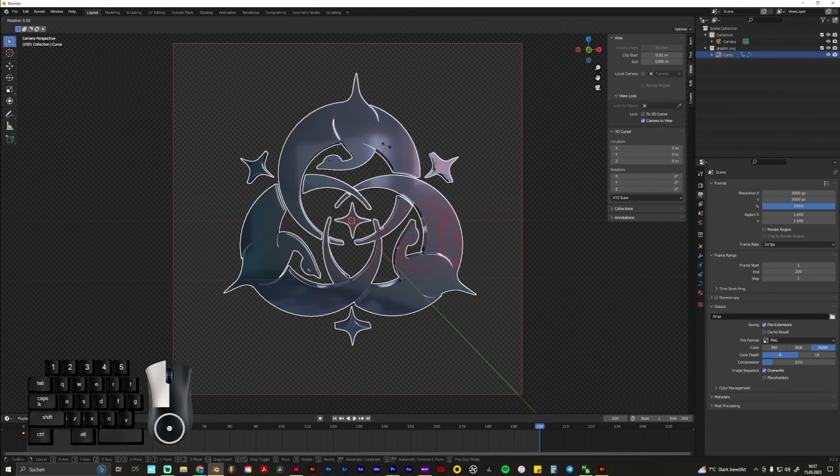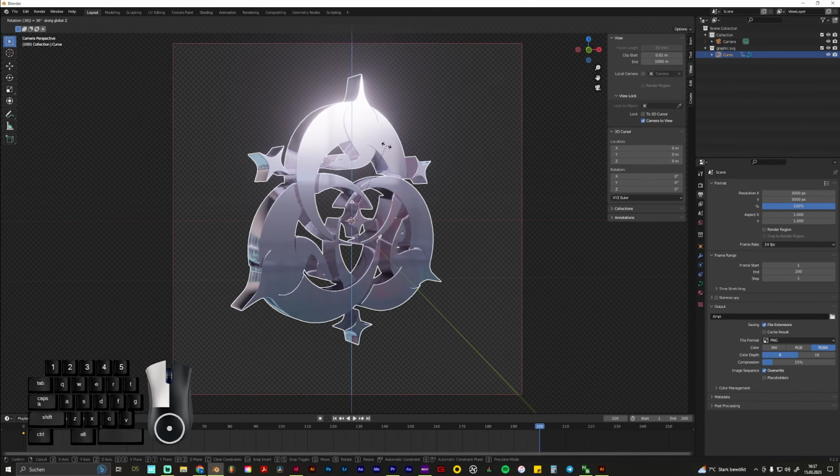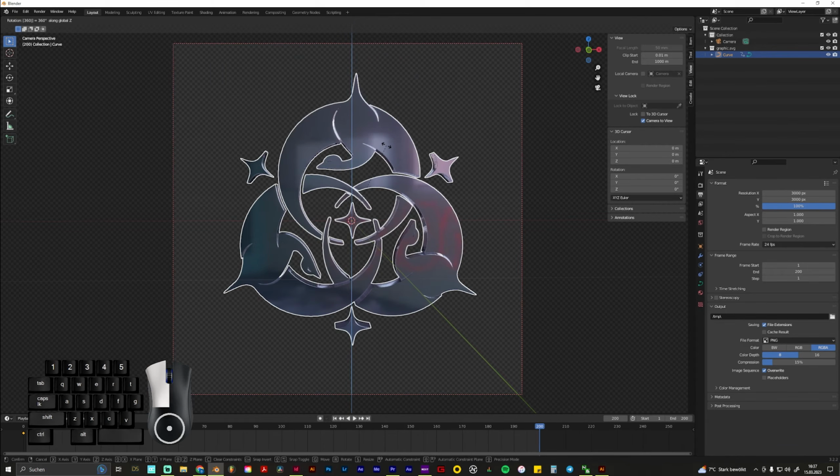It's the Z axis, which goes from the bottom to the top, or vice versa. And then we type in how many degrees it will rotate. In our case, we just put 360, so it will be a whole rotation. Okay, I typed 360, and we can put enter.